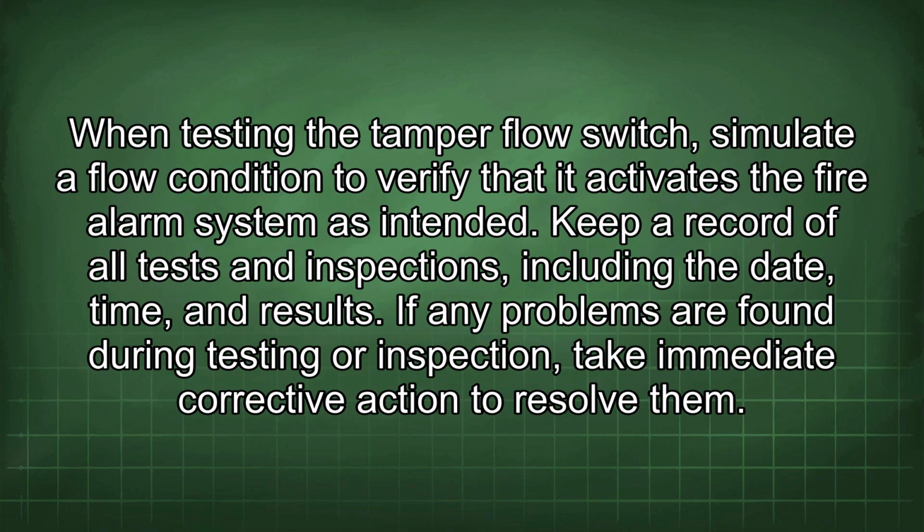When testing the Tamper flow switch, simulate a flow condition to verify that it activates the fire alarm system as intended. Keep a record of all tests and inspections, including the date, time, and results. If any problems are found during testing or inspection, take immediate corrective action to resolve them.